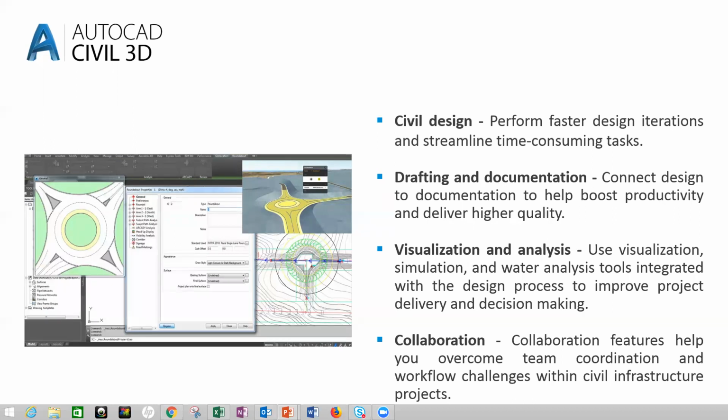You might be creating a layout of a housing scheme and you want to place roads around it as well. And there are workflows where you can also integrate Civil 3D with Revit, and vice versa, to be able to bring your buildings into Civil 3D. And recently in BIM 360, you can send AutoCAD Civil 3D topography up to BIM 360, and then you can retrieve that in Revit using BIM 360 as well.